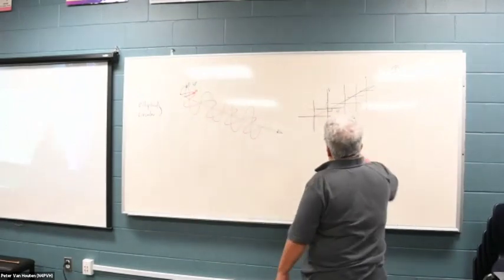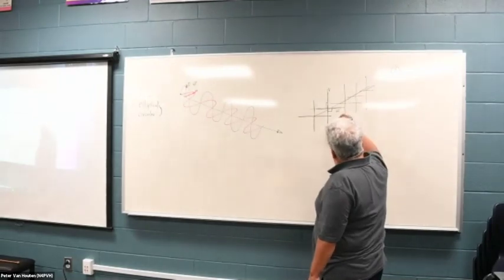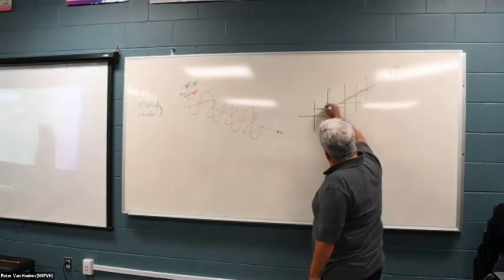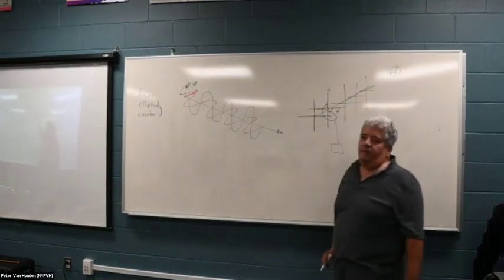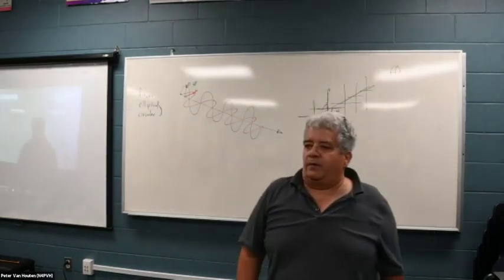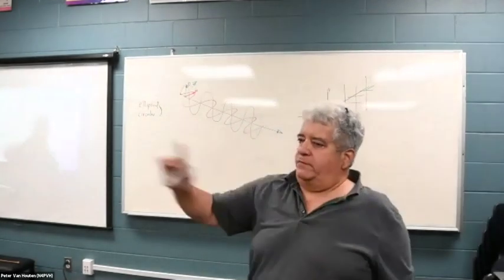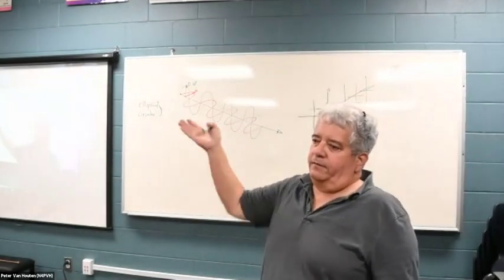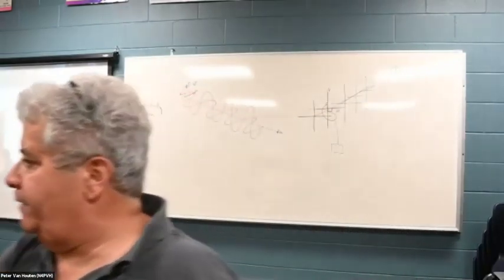Because if we just transmit like this, we have the transmitter here, and we connect a T, goes to this antenna, goes to this antenna. These lengths are the same. I'm not achieving the circular polarization. I'm just getting that combination that showed like a diagonal there on the green vector. It was just oscillating, but in this plane, it was not moving circularly, okay?